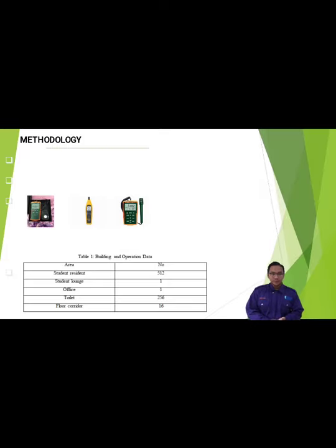For the methodology, all of the data was obtained during the walkthrough audit, including the layout design, the power bill, and technical information for electrical equipment such as air conditioning and lighting system. By following standard audit, two types of on-site measurement were performed, which are room data survey and lighting measurement in each of the rooms in KK4, floor corridor, administrative office and student lounge. The equipment used to measure all parameters was lux meter, temperature humidity meter and indoor air quality analyzer.